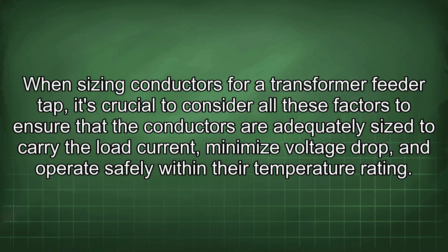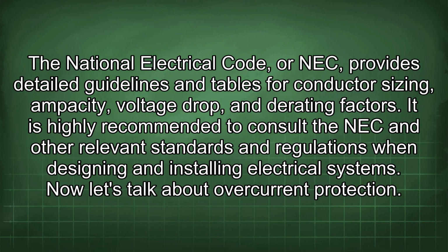When sizing conductors for a transformer feeder tap, it's crucial to consider all these factors to ensure that the conductors are adequately sized to carry the load current, minimize voltage drop, and operate safely within their temperature rating. The National Electrical Code, or NEC, provides detailed guidelines and tables for conductor sizing, ampacity, voltage drop, and derating factors. It is highly recommended to consult the NEC and other relevant standards and regulations when designing and installing electrical systems.